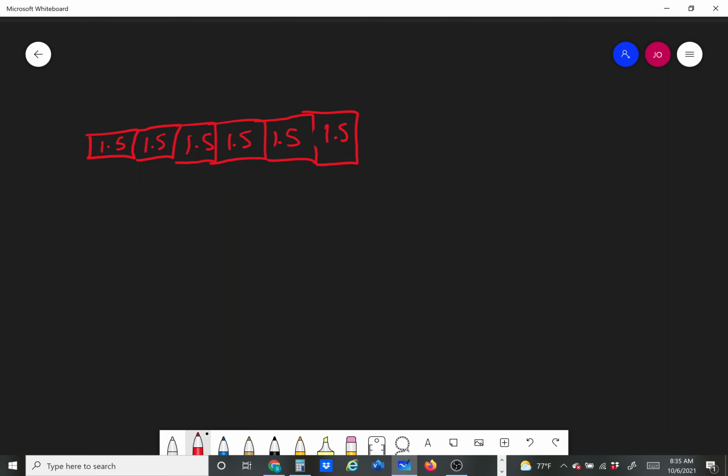So with my 6 1.5 volt batteries, that means I've got 9 volts. But we also know that these are 1.25 amp hour. I'm not going to draw them out. We know that amperage is the same in series. So what I have when I hook up these 6 batteries is I've got 9 volts that is good for 1.25 amp hours.